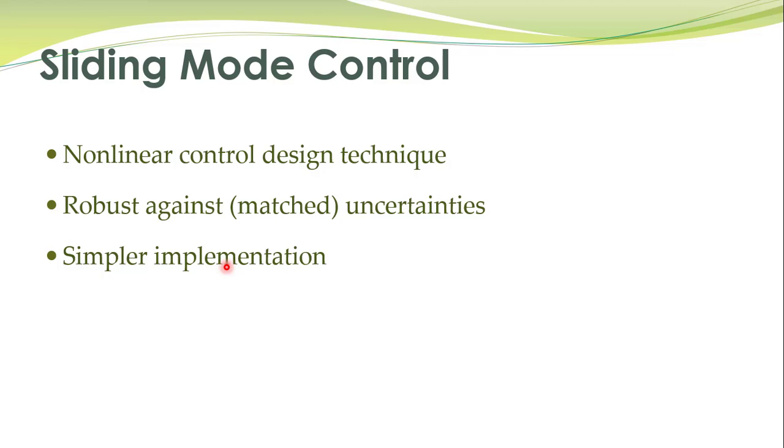We have already designed controllers using feedback linearization techniques, and later on we shall also study the backstepping approach, and we shall see that with this approach, the controller that you finally get is much simpler as far as implementation of the controller is concerned. There is one disadvantage of this approach, and that is that it is associated with chattering.